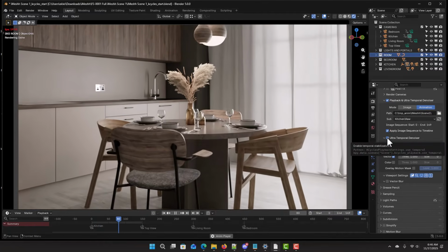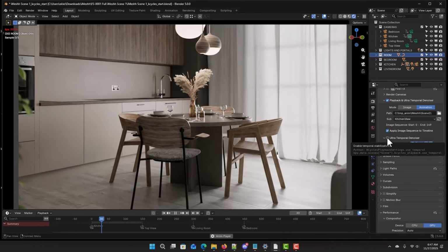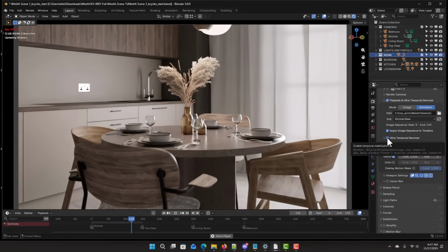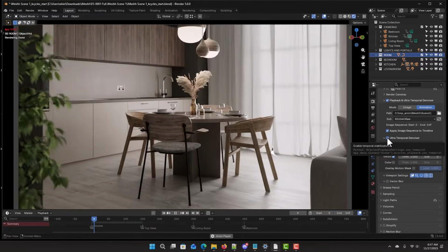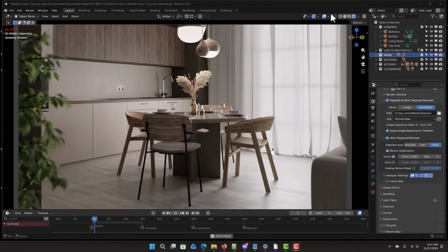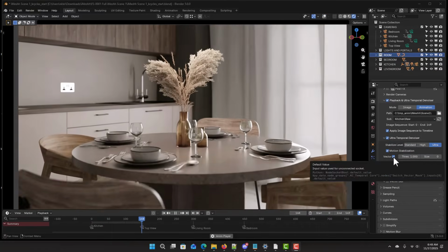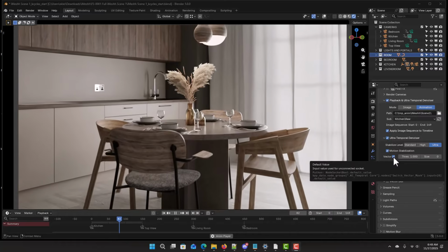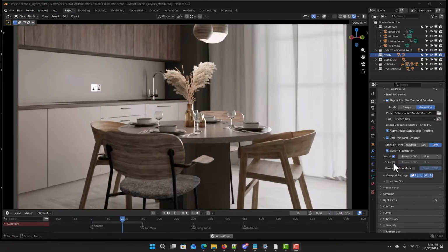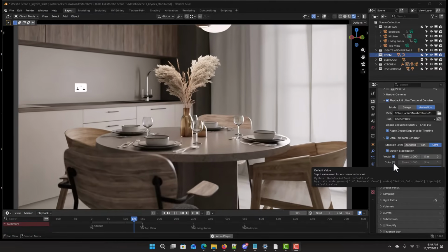Toggle it back off. See how much flicker in the glasses and the plants there are. You toggle it back on. It becomes solid and stable. So there's a huge amount of flicker reduction and temporal artifacts get reduced. It's a little bit faster if I turn off the overlay settings completely. The vector motion is the amount of ghosting and motion artifacts that you get when you're stabilizing the scene. The motion color is rarely needed and should be off by default, and it can be combined or done separately.